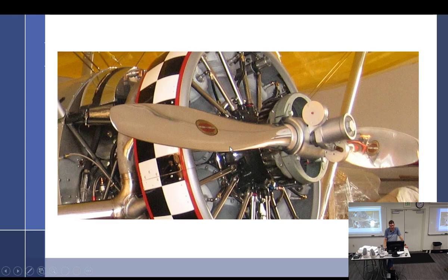But either way, it's going to be either high or low angle. So if I have it in a low angle, that's going to give me what kind of RPM? Higher RPM or lower RPM? Higher RPM. So higher RPM, lower blade angle. That's kind of like what gear in a car? First gear. So that's going to be for takeoff, climb. Then we get up there, we're going to shift into a higher gear, pull it back, we're going to go to a high blade angle with a lower RPM.